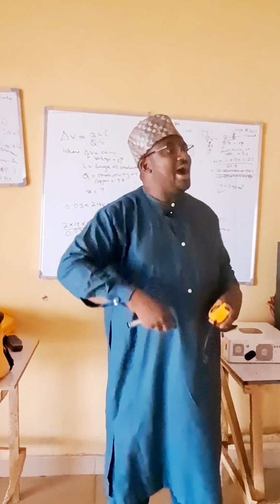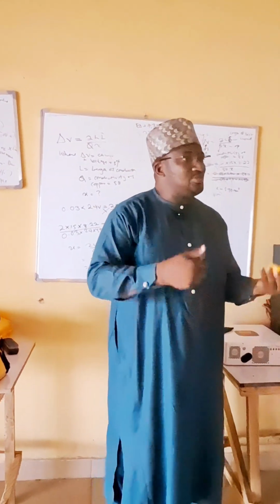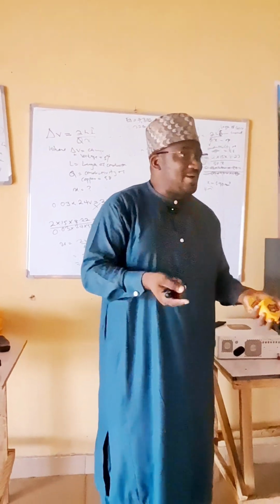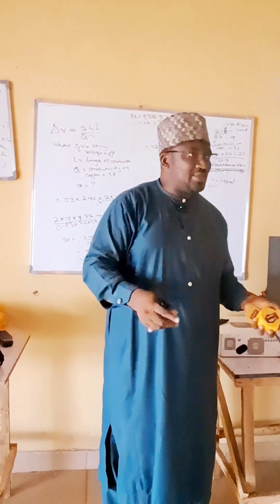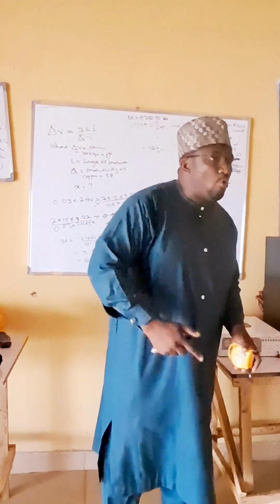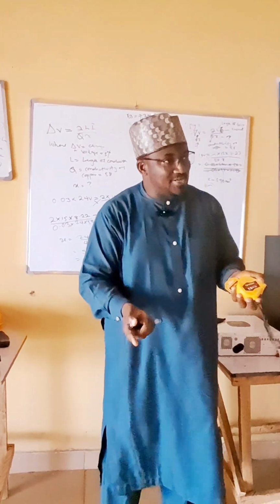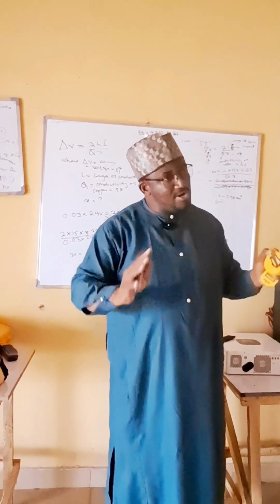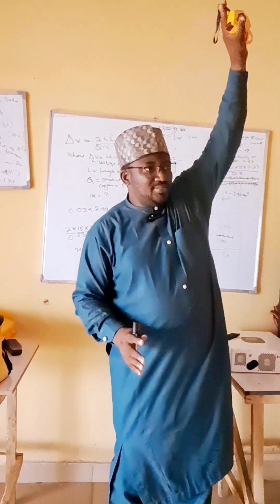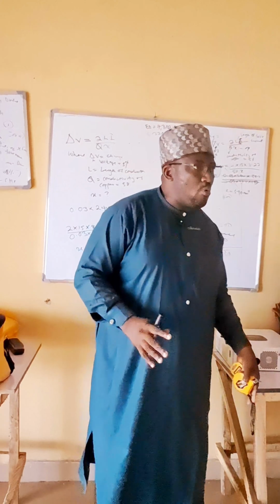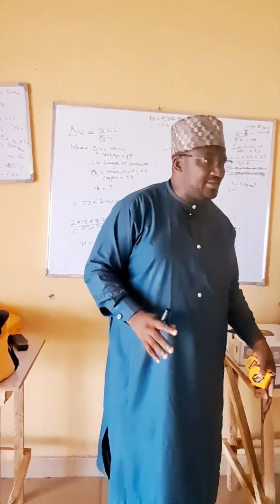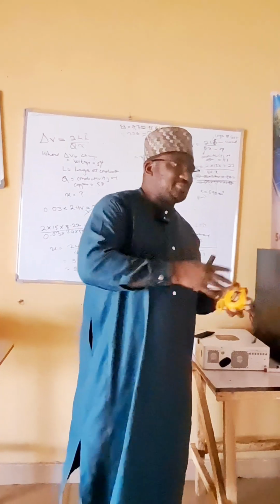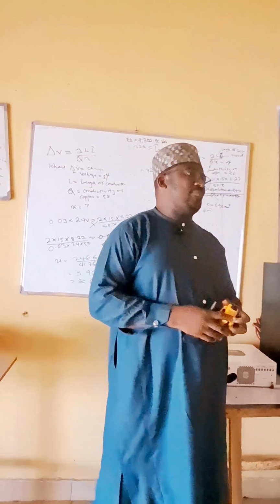So you still have to consider how many batteries you are dealing with. Is it 2 batteries? 4? 8? If it is 8 batteries, what is the configuration of connection? Is it a series connection generally, or do you have to do series and parallel connection? So you have to consider all those cables. Cumulatively, let's say you have 3 meters, plus downward 10 meters, that is 13. Then connection of batteries and so on, let's say you take 5, you sum them. So that is your total length of cable to be used.